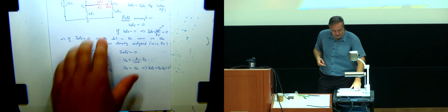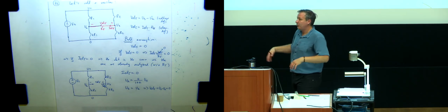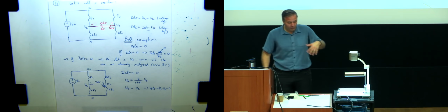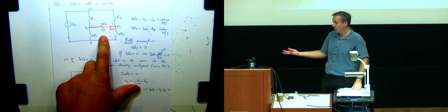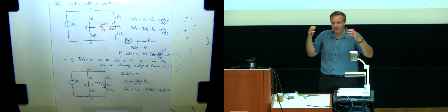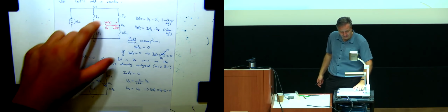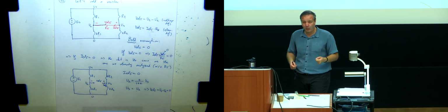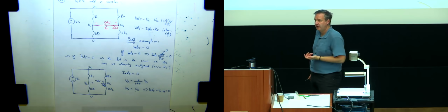Right? And the reason why we want this real R5 here is because we're building up toward this bigger, more complex model that will reflect how the touchscreen really looks like. Right, so then, when we look at how the touchscreen will look like, you're going to go, oh, I know that circuit. It exhibits this kind of behavior, right? And the macro behavior is that, hey, as long as these resistances are in the same proportion, regardless of the resistance across, the nodes are at the same potential. Right?